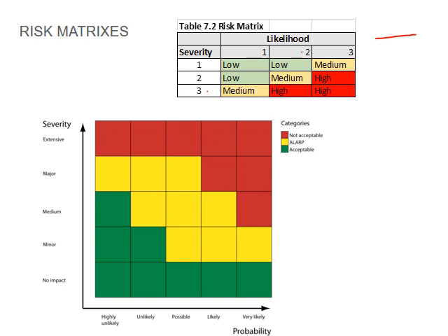So instead of just putting up danger tapes, you may put up barricades. So in this instance, your risk will be highlighted as a high. It might even be a 3, which will also highlight it as a high, but because it is quite a severe incident, even if the likelihood of it is quite low, you will still sit with a medium high risk. So that's the thought process that one goes through in identifying the risk priorities on site.